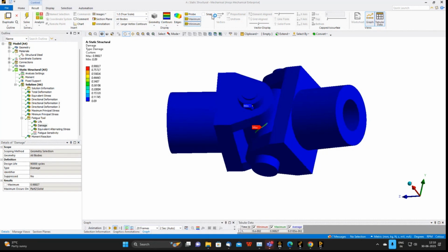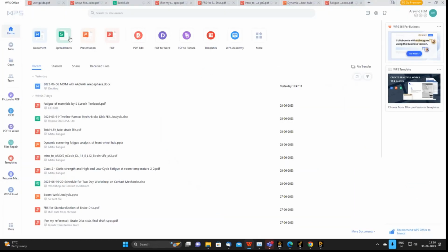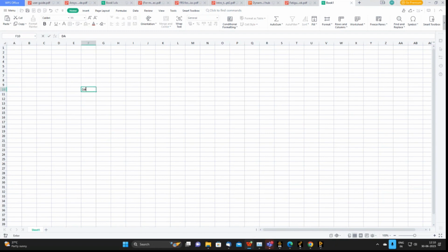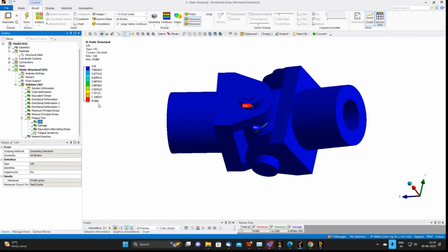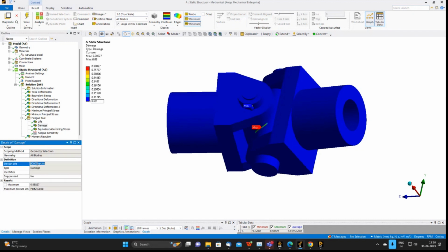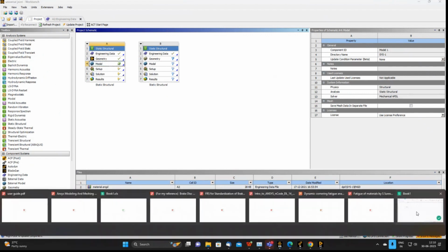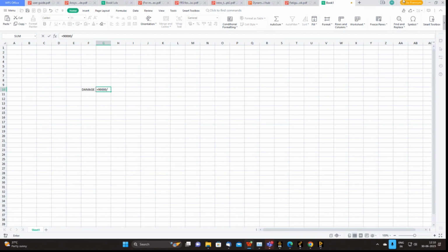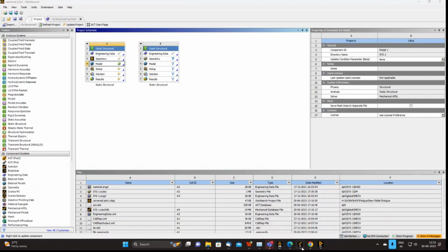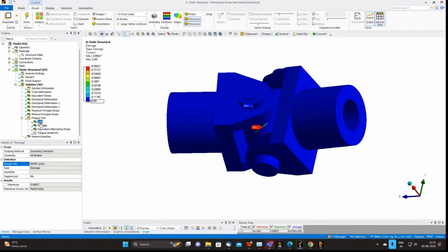So damage is coming high. That is my concern. If it is within the failure cycle, then the damage is within one, right? If the cycles you are giving are high, then the damage also needs to be high, right? Yes, sir. What we are seeing here is below the 90,000 cycles. If you are giving 10 to the power 6, then the damage will also be high.